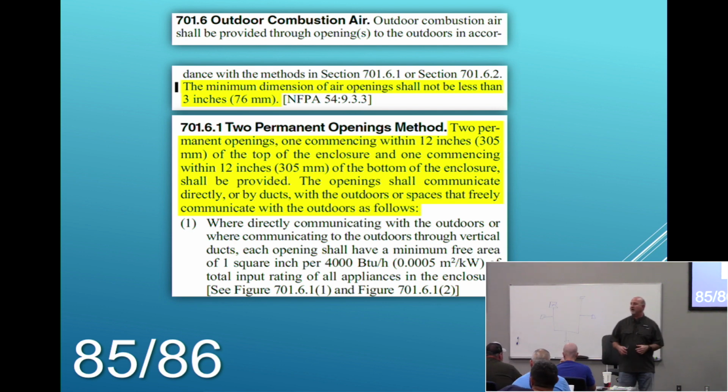So let's talk about that. If I've got a duct going through the ceiling, you can see my duct. If I've got a duct going through the wall, you can see my duct. But do you agree if I take that door over there off the hinges, you don't see any duct work, do you? That would be an example of freely communicating with the outdoors or freely communicating with a space that communicates with the outdoors.